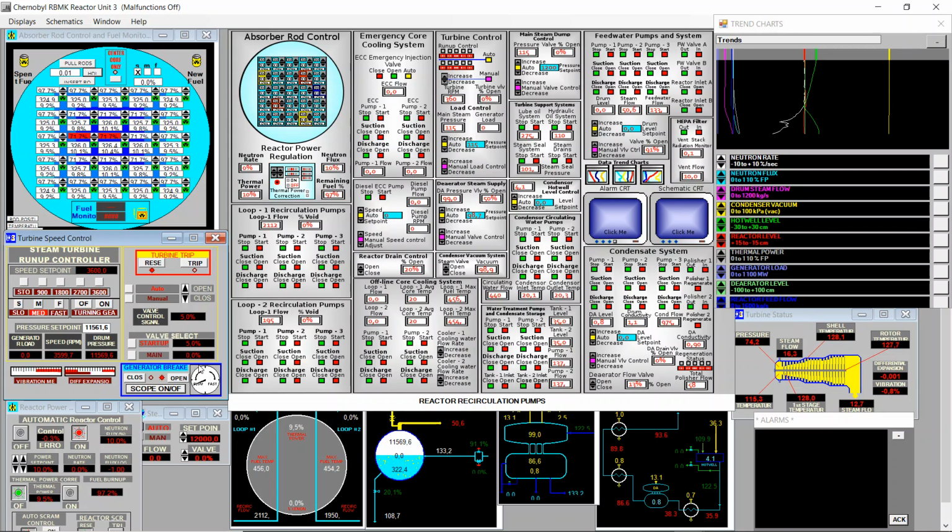So if it's rotating in this sense, clockwise, we'll need to close the brake just a bit before 12, like at 10 o'clock. And if it's counterclockwise, we will need to close the brake around 2 o'clock. But it also depends on the velocity it is rotating. So this is a bit tricky, and if we don't get the point right, we'll create a turbine trip. So I will close it now. And it went smoothly. The turbine is now connected.